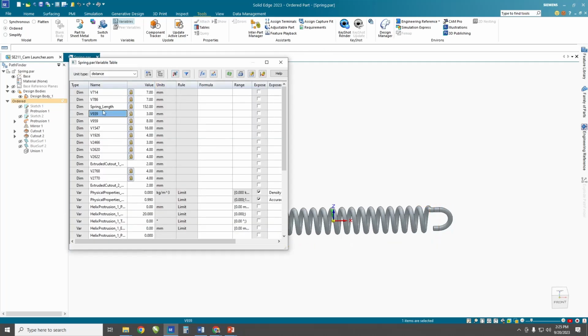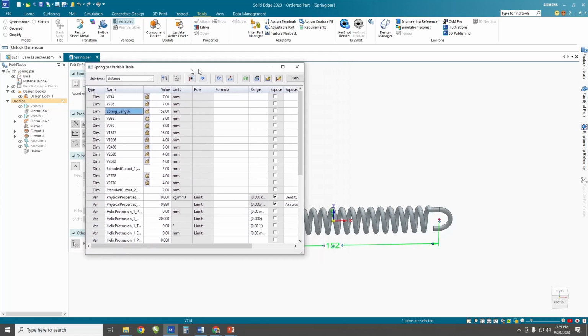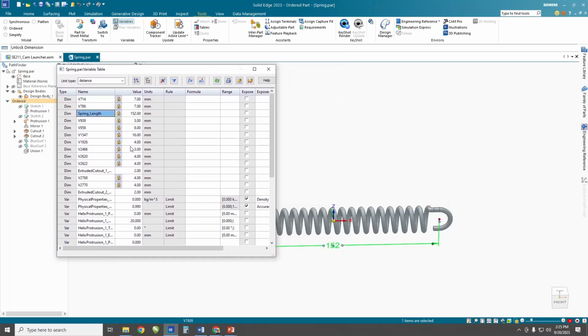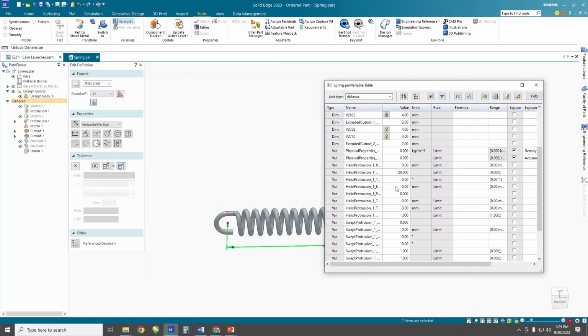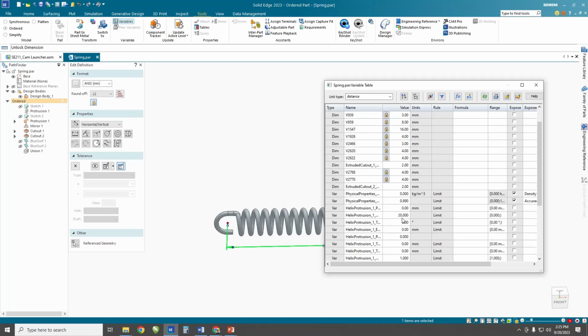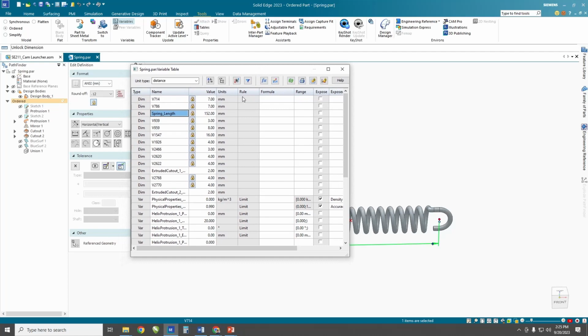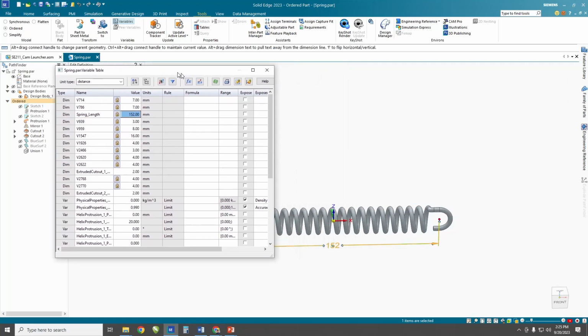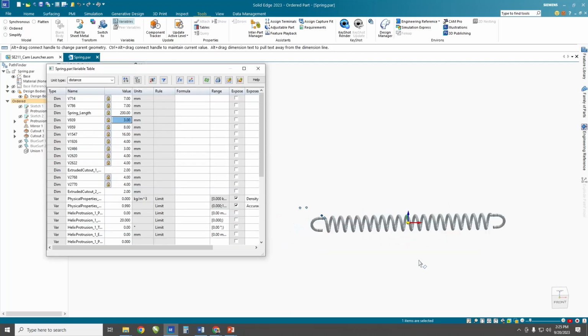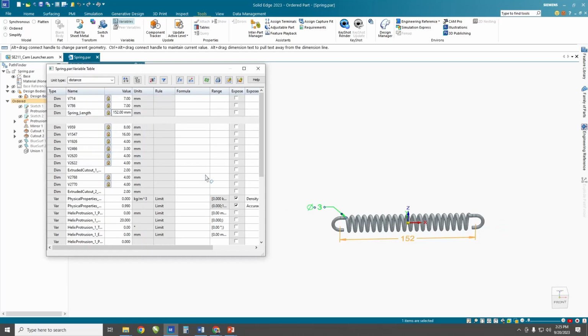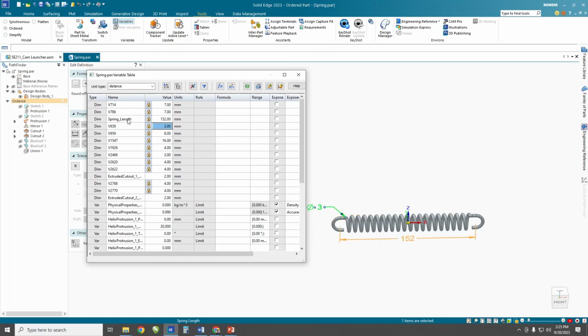All right. So it now has a name that I can trace what it's doing with, but you'll see everything in here has a variable. And it's all listed here. So all the different things you can find here, and you can see which ones of them are locked, which ones aren't. We could change them from here. So this is like a one-stop shop. I could from here change this to 200 and it'll automatically update there. Okay. So this is what we have here with the variable table.